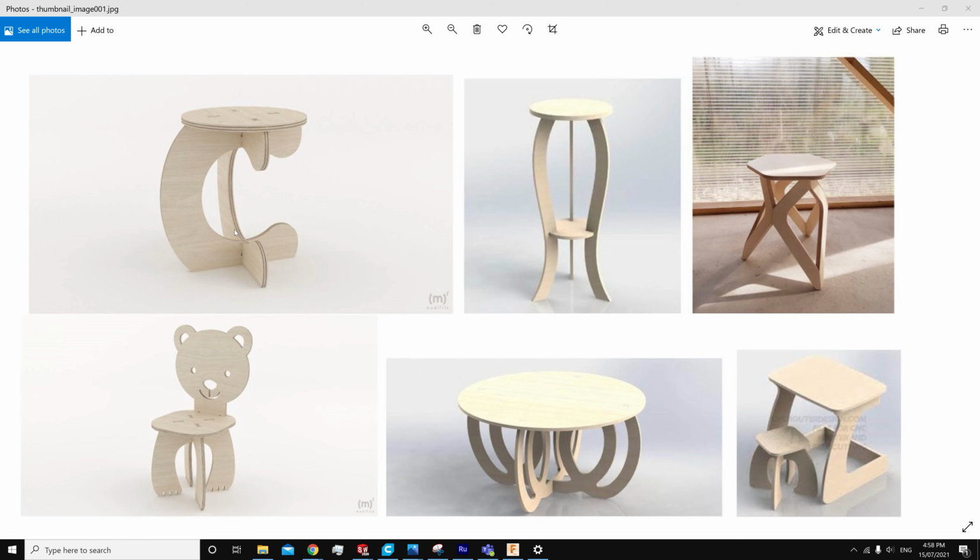Something else to think about is maintaining the structural integrity. We're going to be going with a birch plywood of about 18 millimeters. And birch plywood, although it does have lots of ply layers, many more ply layers than conventional non-structural or CD pine plywood, still isn't going to be as strong as a steel chair leg. It will still bend. So you'll have to think about how you can minimize the length of the legs, or at least maximize the width.